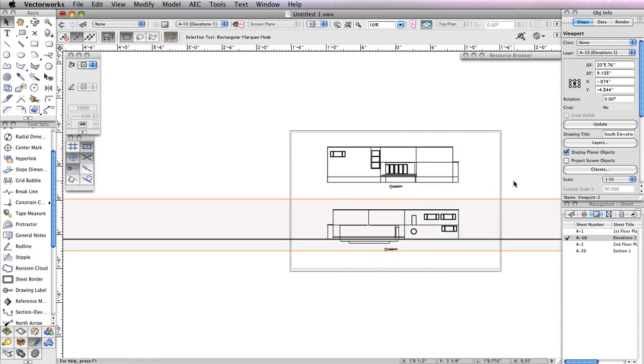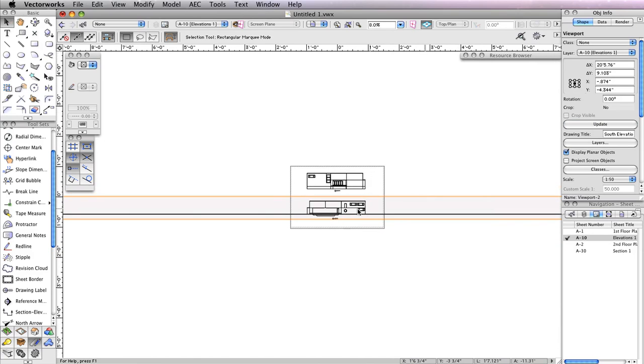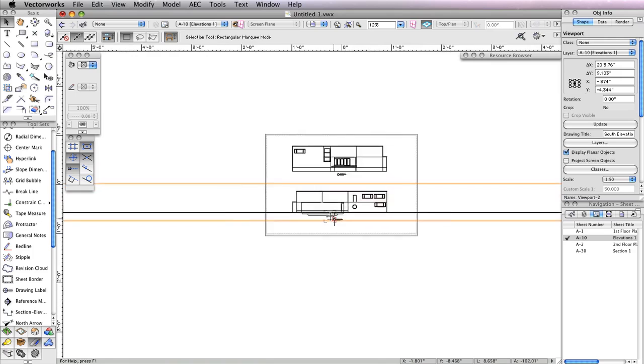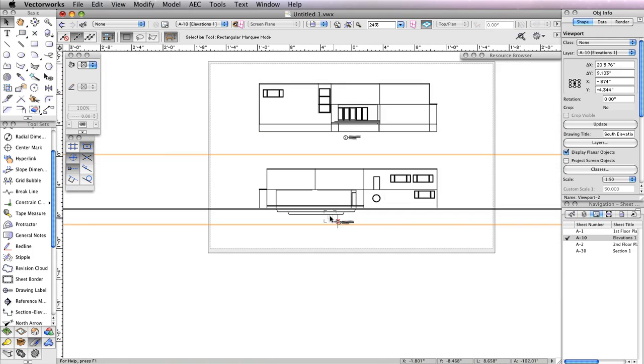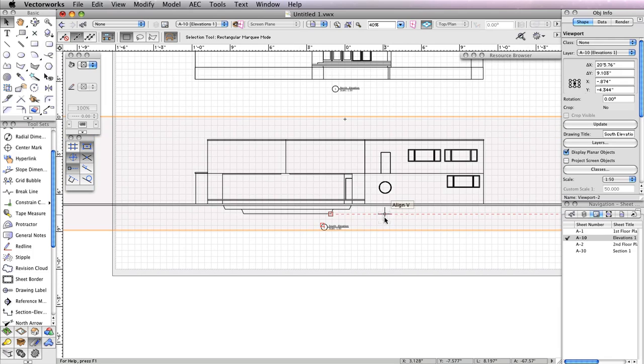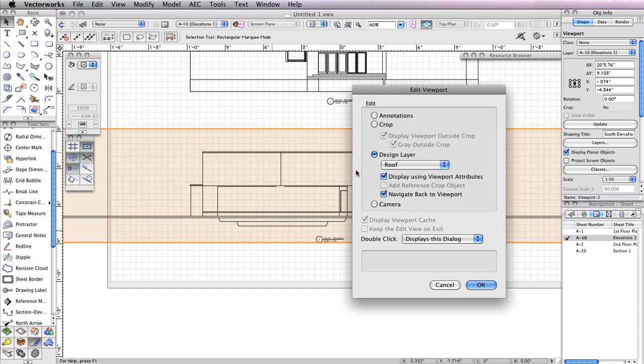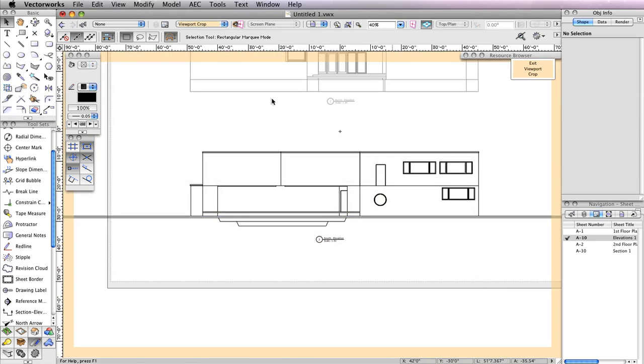You can see that the ground extrude currently extends much further than the page boundary, and that the circular floor from the auditorium is protruding through the bottom. The best way to fix this is to crop the viewport. To crop the viewport, right-click or double-click the viewport and choose Edit Viewport Crop. Then, using any 2D shape, in this case a rectangle, draw your desired crop box.